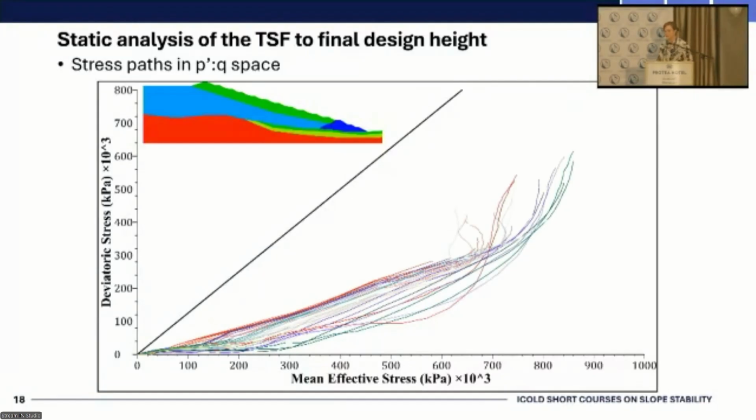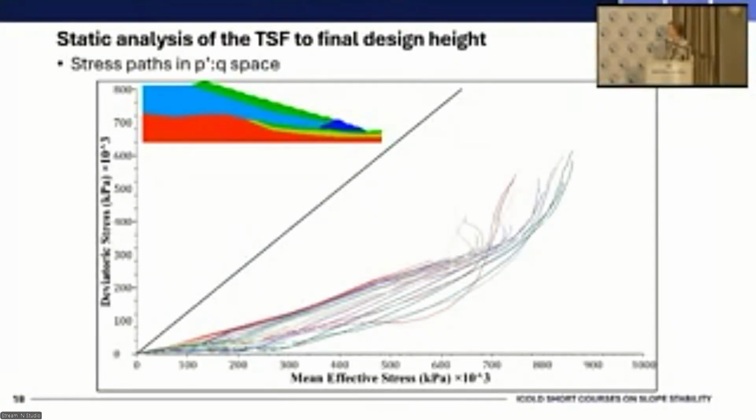and what is interesting to note is that these points over here, they sort of deviate from that general trend, and those points over there are located towards the toe of the facility, and what's actually happening there is that they are laterally far enough away from the application of the tailings on the tailings dam to not be affected by the vertical load, but there is an increase in the shear on those queried points.